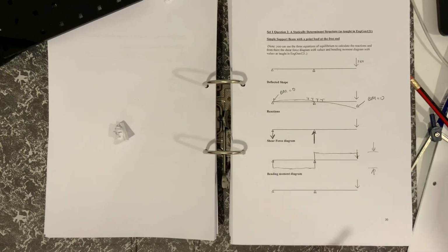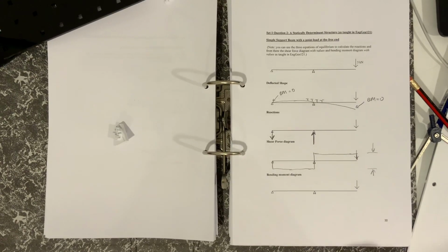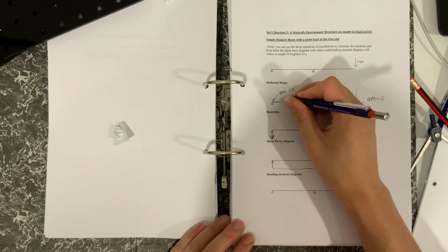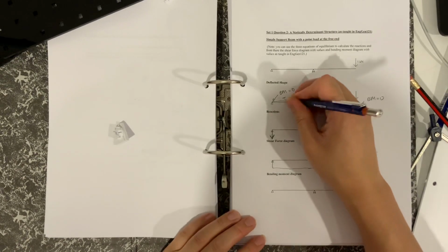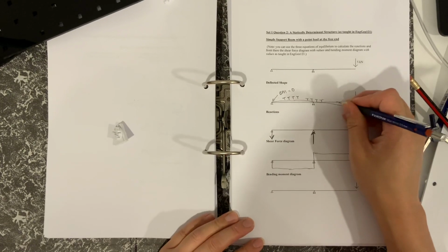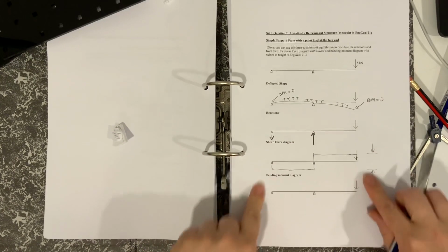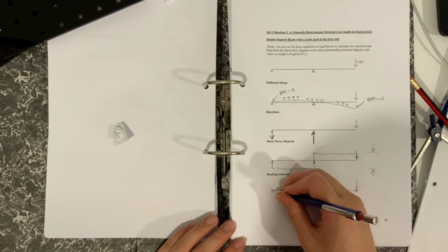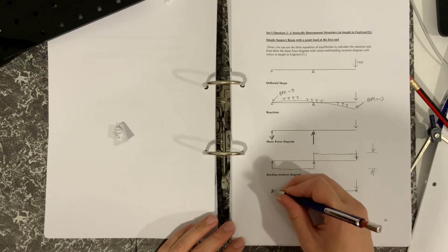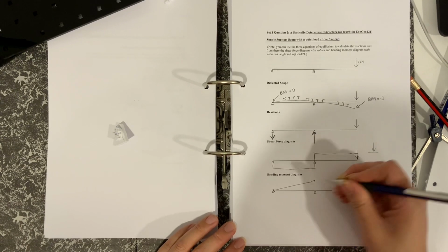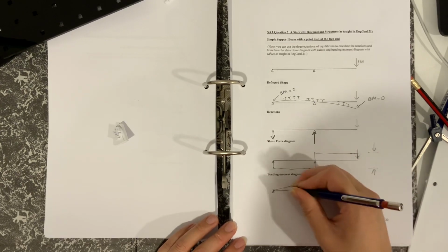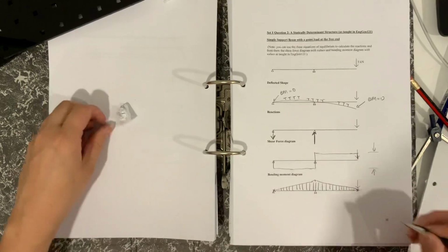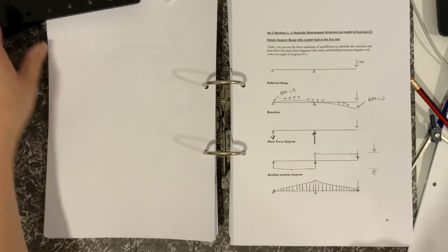Okay. And then finally we get to the bending moment diagram, and so the bending moment diagram would look like here. You can see the tension is going all the way up here, and then down here that side's in tension. So the whole thing's in hogging. Bending moment there is 0, bending moment there is 0, and then bending moment is maximum over here. So we would get a bending moment diagram like there, with the whole thing being in tension.